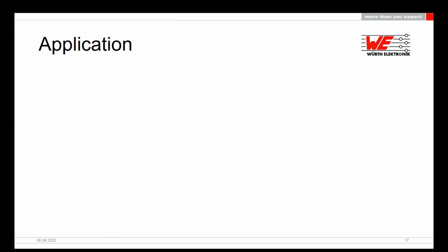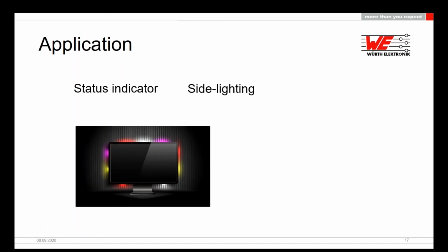Our side view LEDs belong to the low power category. They are mostly used for the indicator. As its name says, this LED is designed for on-site light applications. In most cases, the side view LED is placed at the edge of the PCB. It's easier to guide the light out of the PCB, such as in the application of ambient lighting or in coupling with the optical fibers.